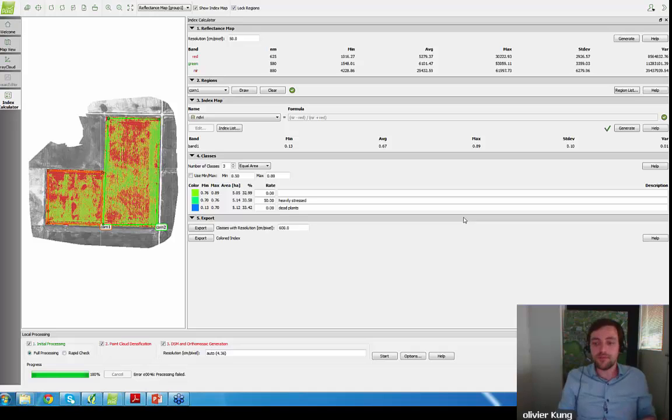There are a few ways to compensate for this. One of the first ways is to use one of these sensors that is looking upward, that measures the amount of light. By measuring the amount of light during the flight, you're able to measure how the light is changing, and by measuring how the light is changing, you're able to compensate for it. One of the cameras which have this system, and which we have heavily tested and works nicely in Pix4Dmapper, is the Multispec 4 from Sensefly. This camera writes the data about the amount of light inside of the images, and Pix4Dmapper is able to read this value and compensate correctly for the different amounts of light. So this is one of the ways, but for that you need specific cameras with specific sensors to make this work.